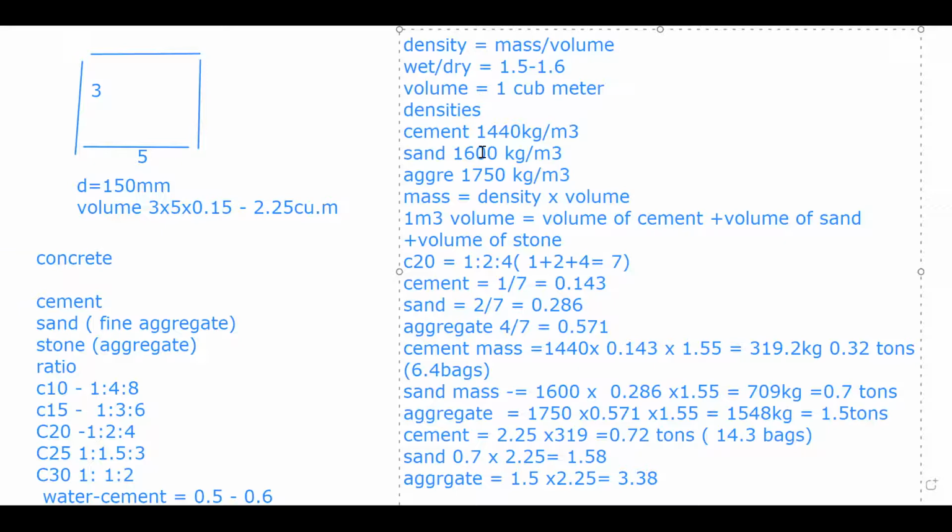You see, concrete is about 50,000-60,000 per cubic meter, depending on the grade. But reinforced concrete is about 80,000-90,000. So the other one now comes as a concrete, and that is the cool thing about this class, because I'm going to show you nominal design. Once you get the volume of your concrete, you can automatically deduce the kilograms of reinforcement. You don't need to start doing a bar bending schedule, though that is the normal thing to do. But believe me, I have done it severally.